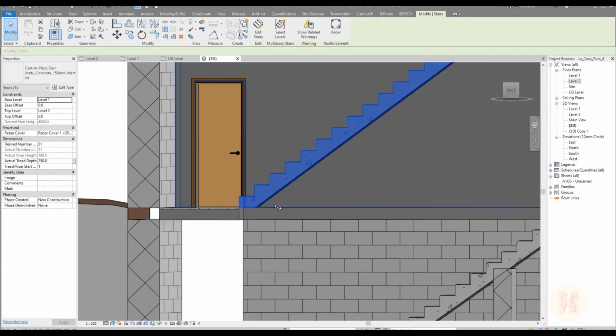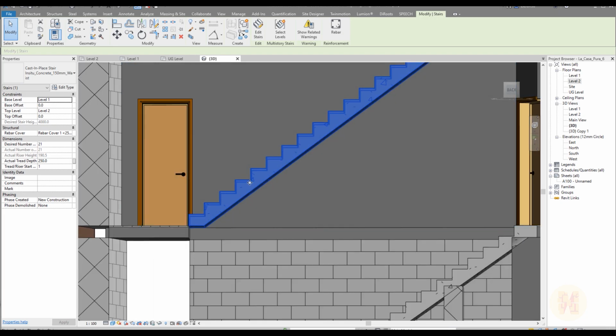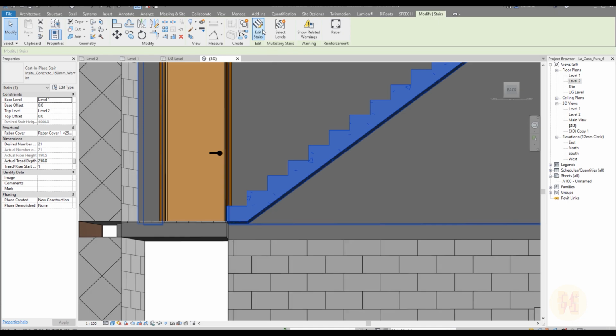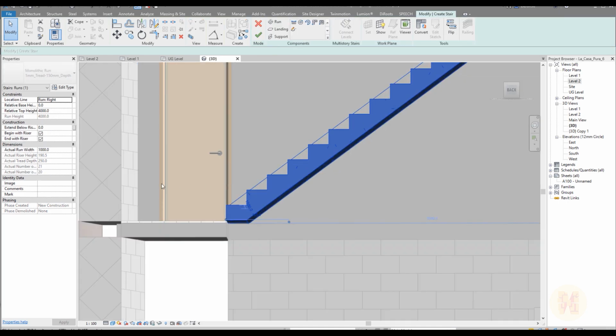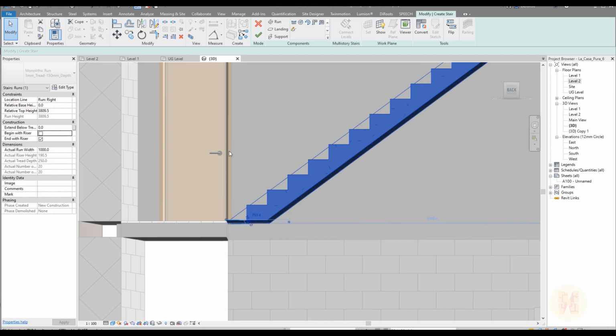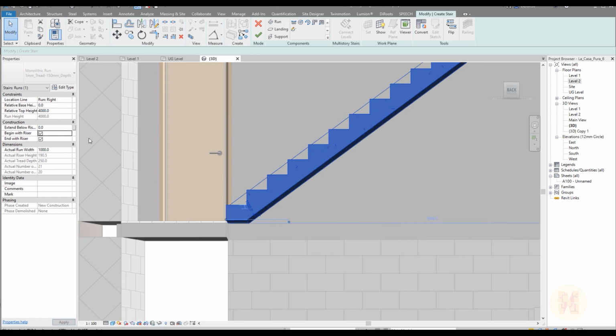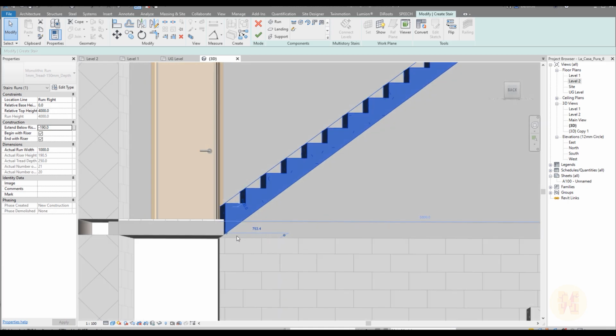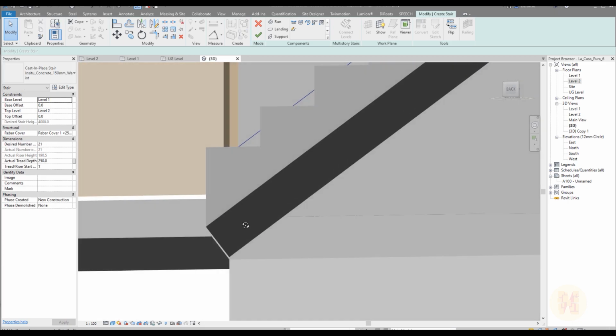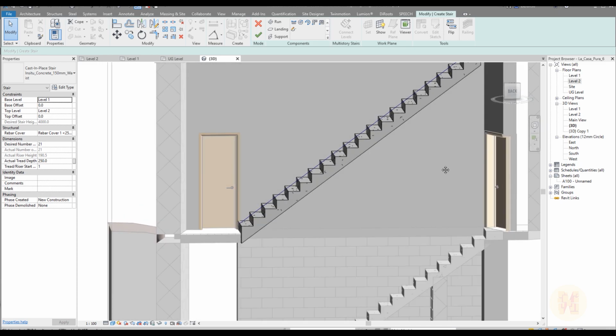So you can select your staircase, go to edit staircase, select your staircase, and for example begin from the rises. You can uncheck it and place it more deeply, or you can make extend below, so you can say -100 like this, and as you can see, it's starting to connect. So you can make it like that if you want.